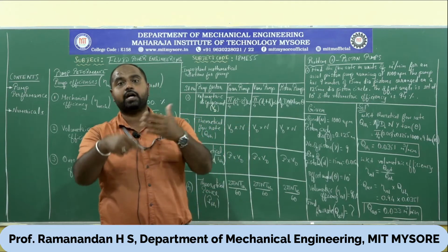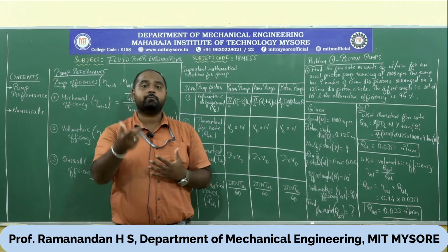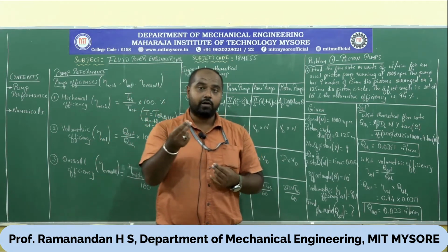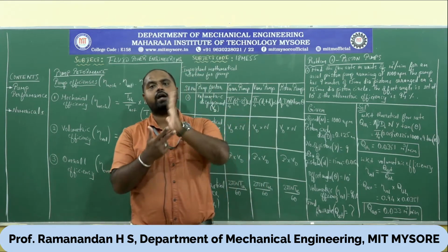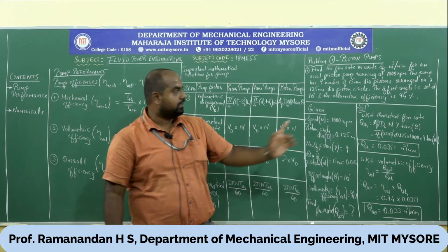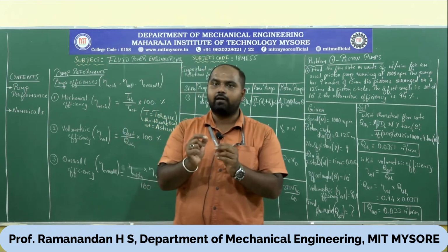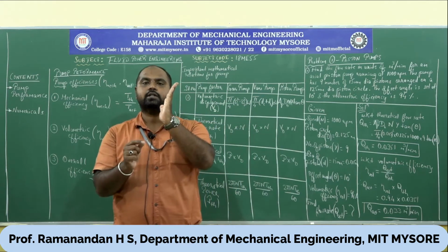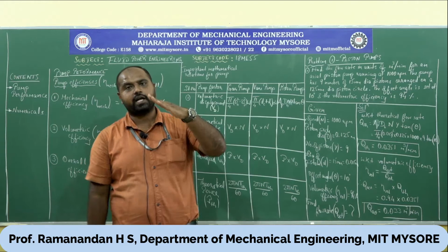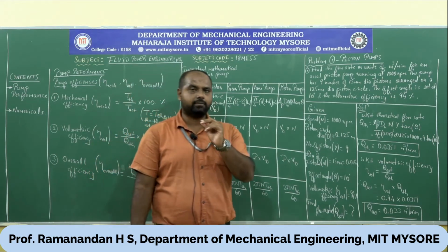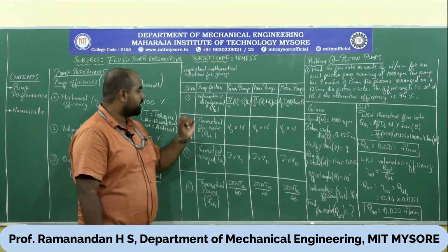Then you have speed of the shaft, which is one of the important parameters for suction of the fluid. Then comes how many number of pistons. So that will give you volume of pistons. Finally, the angle of the swash plate, theta. Theta is nothing but the offset angle, or the angle of the swash plate, or if it is bent axis, the offset angle of the cylinder. So this is about volumetric displacement.